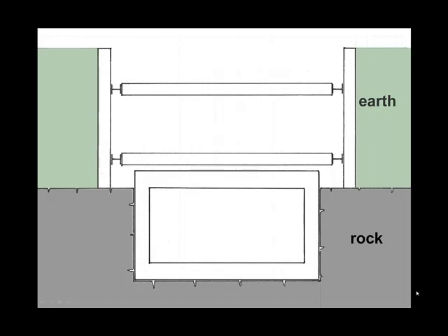On this project, the earth portion was typically supported by soldier piles and lagging or secant pile walls. That upper portion was braced by pipe struts or rock anchors or some combination of those two. So much of that material has been covered, and you will see applications of it again on this project. The lower portion was in rock, and the rock was removed by drilling and blasting.